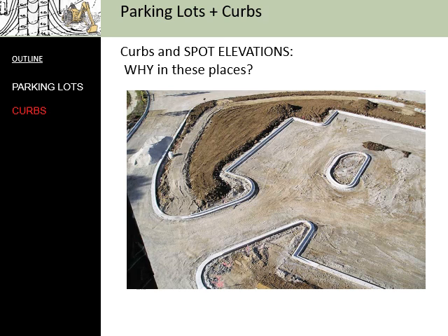So there are quite a few places that we're going to need spot elevations, and we just went through a list of them. To begin with, we know that we need spot elevations any place there is a corner. And so we know that these corners all need spot elevations. We also know that we need spot elevations any place we have a straight line that then changes to a curved line. So all of these locations need spot elevations. And yes, there are quite a few of these that we're going to have on a parking lot.